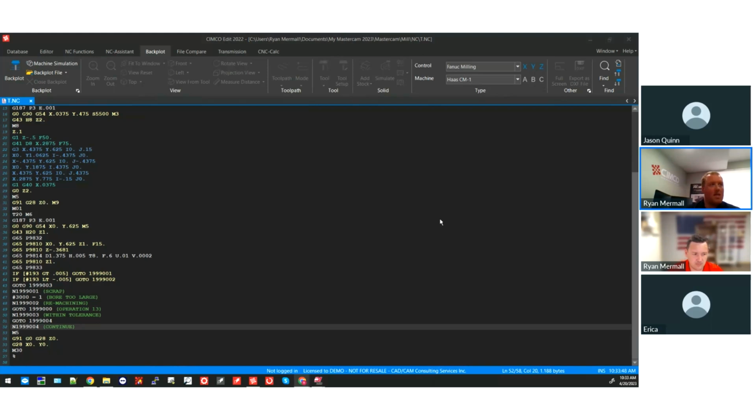Then I would recommend taking either the deviation or actual, storing those two specific variables, and then you'd be able to say this variable plus this variable divided by 2 gives you the average between them. And that FANUC Macro B is totally outside of CIMCO, correct? It is correct. Yeah.